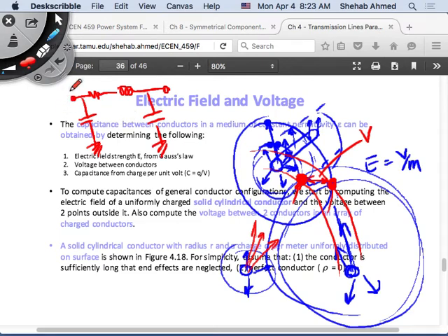No. So I only want to calculate the capacitance between the line and the ground. There may be capacitances between line to line, and there may be inductances between line to line, like the mutual inductance. But sometimes, when I'm drawing 3-phase circuits, we don't consider mutual inductance in the calculation.